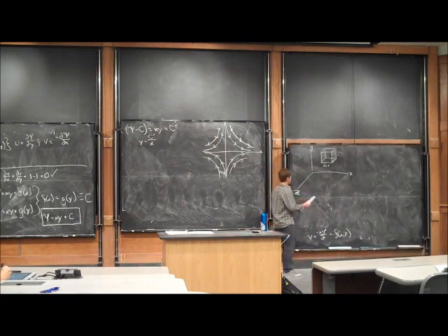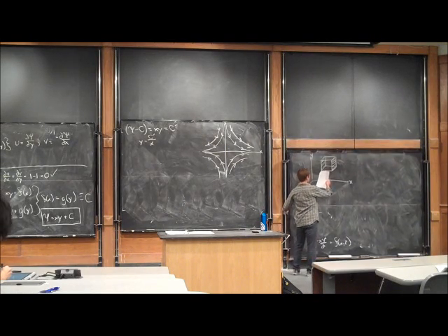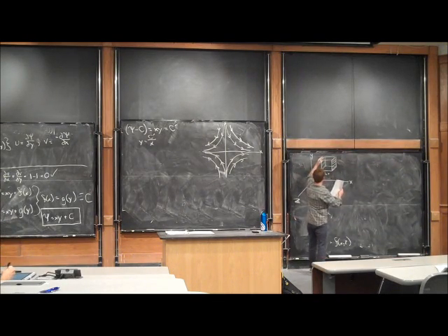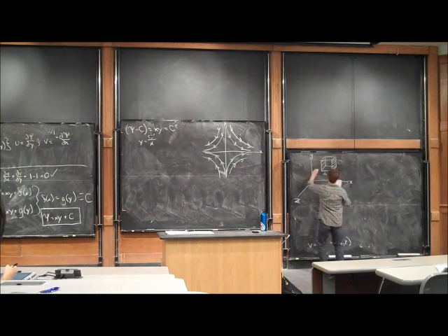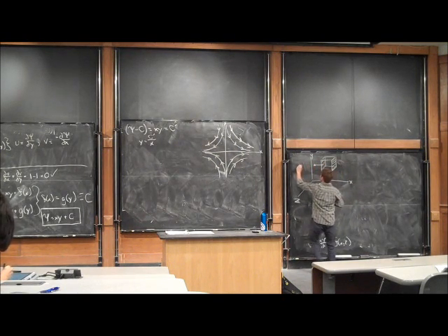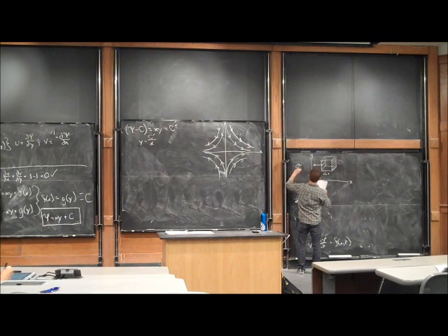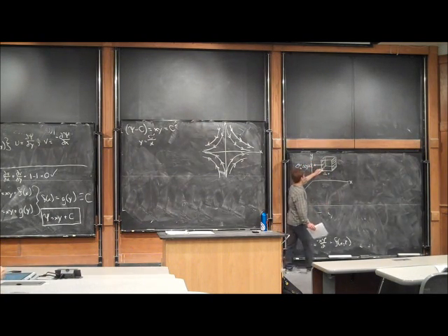So I can say that acting on this, we have some surface area given by delta z, delta y, and we're going to have some stress acting on it times delta y, delta z. So this is a force. This is some stress acting over this surface element times the area of that element.